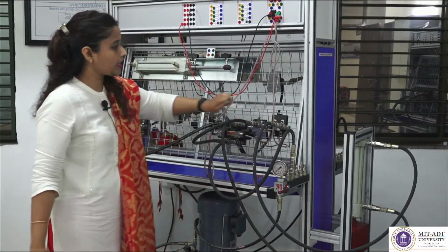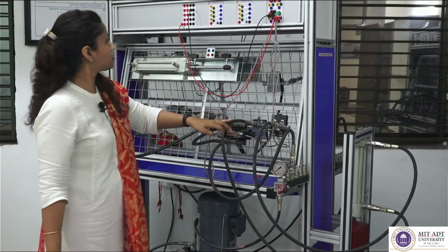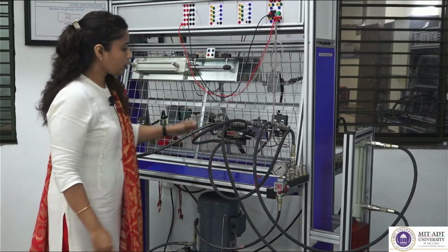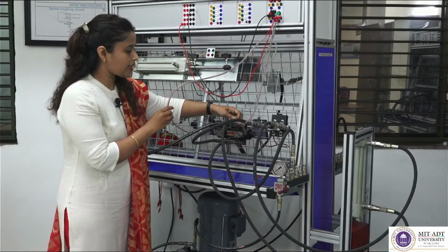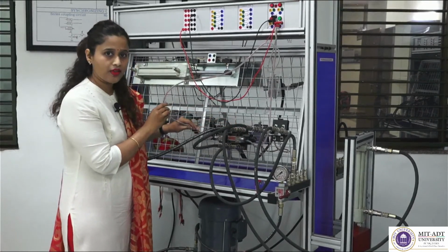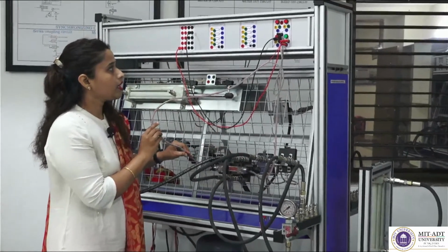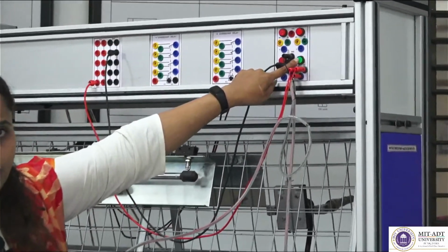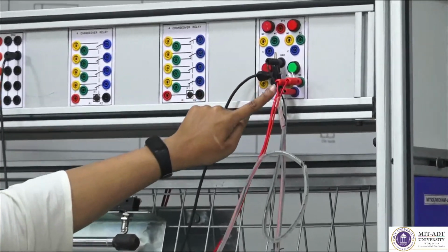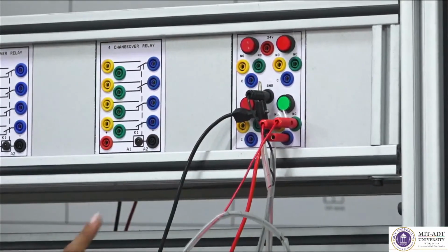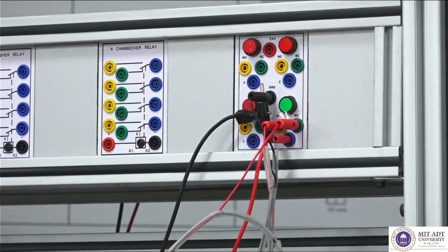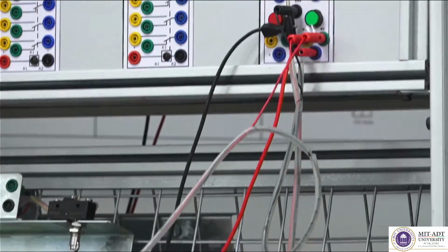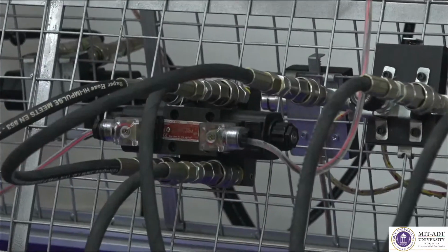So, I am just quickly starting the whole circuit. Okay. One more thing I would like to explain over here, both sides solenoid operated 4/3 DCV is there. So, I have done all the connections for latchable push button. So, here you can see that the same connections I am using it again and again in order to just switch over both side solenoids, and I need to switch quickly over the extension and retraction stroke of the cylinder. So, I am starting the whole circuit.